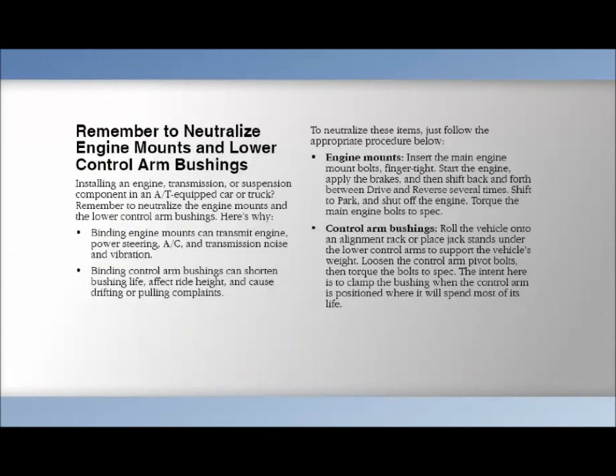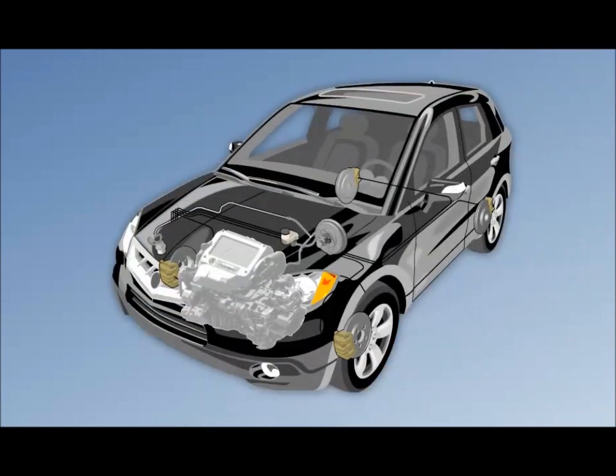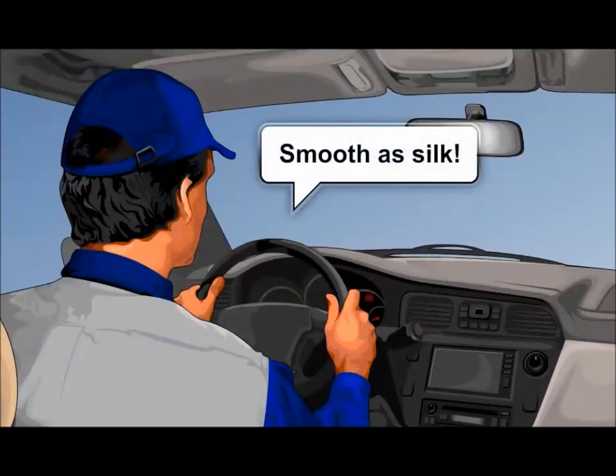If the engine mounts are out of alignment, a service news article includes a mount neutralization procedure. This procedure places the engine in the correct mounting position, allowing it to move freely without transferring vibrations to the driver's compartment.